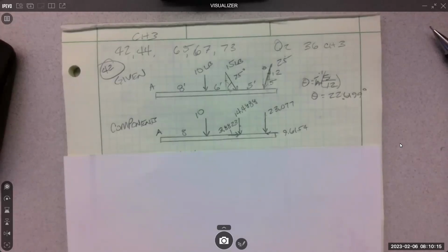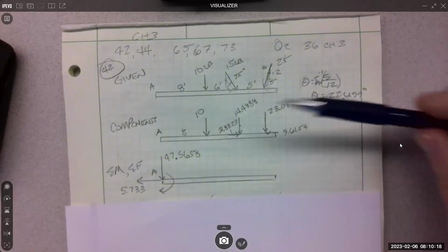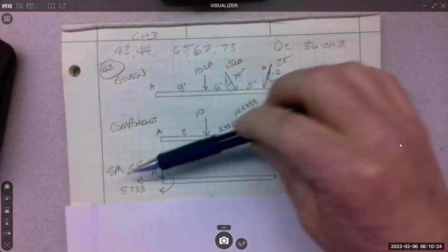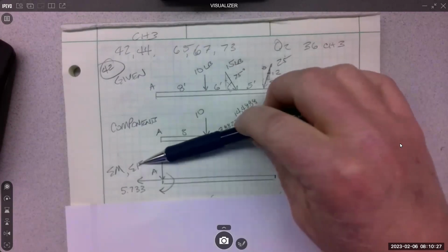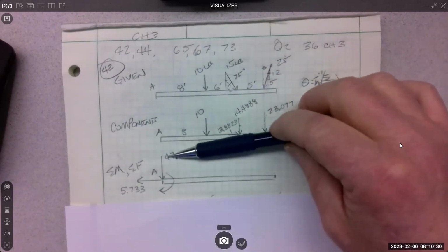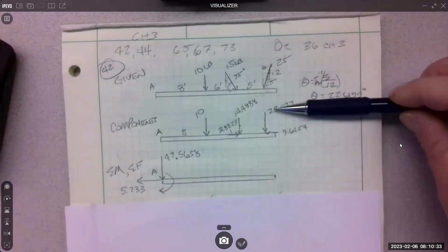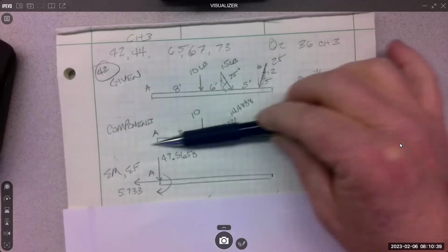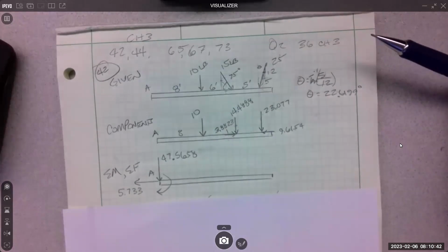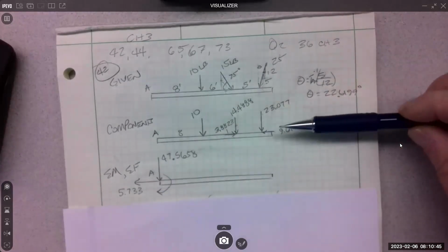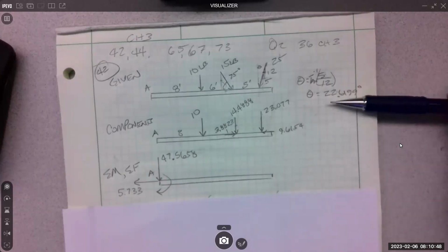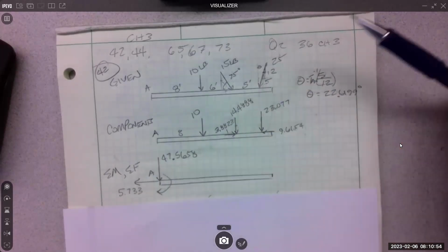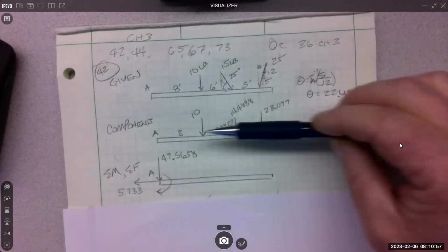All right. Once you get it into components, then you collect everything. Everything moves over here and I collect. I literally sum the moments and I sum the forces in both the x and y. Forces in the y, that's the 10, the 14, and the 23, and they're all going down, so they add up. That's just adding that, that, and that. Same with the x. There's two of them, they oppose each other. So we got 9 here, 3 here, should be close to 6, right? So then I just add up the x's. Everything gets moved over to A.